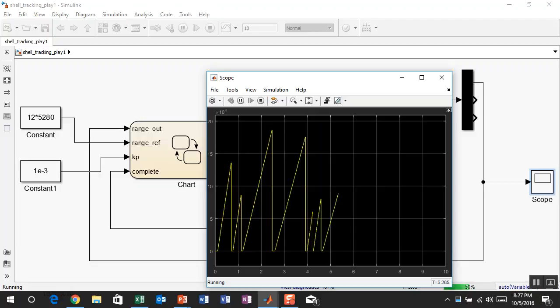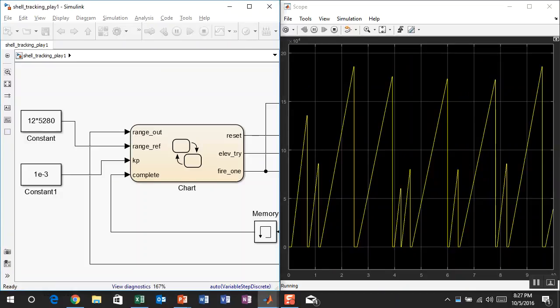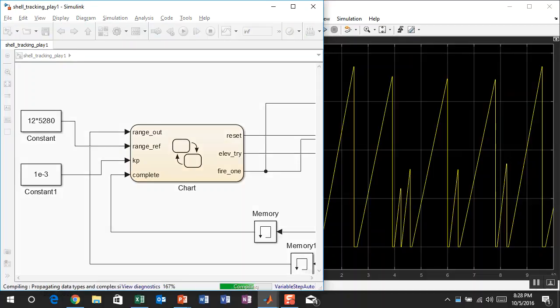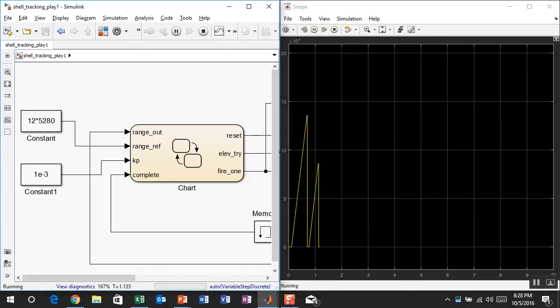That's interesting. It is solving a whole bunch of times. But I think our constant's still too big, our KP value. So I'm going to put this over here. And I don't know if you guys have seen this yet, but you're going to like it. So we can make our solve time infinite, our end time, and just let it run and change parameters. So I'll pull this back so we can see what's going on.